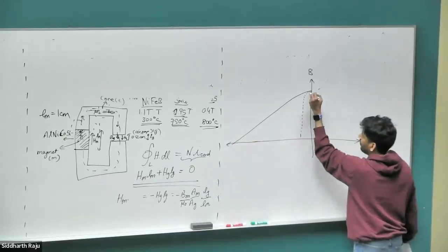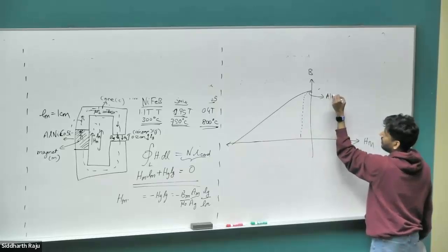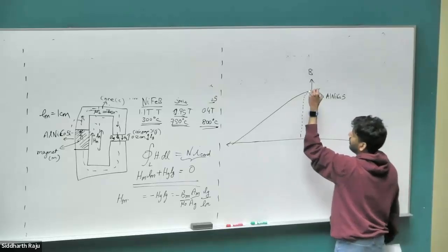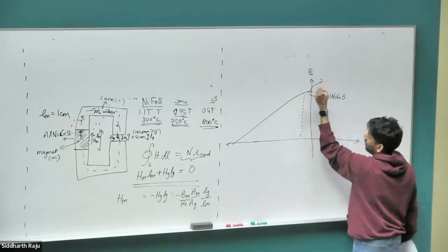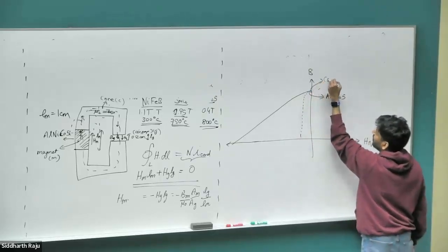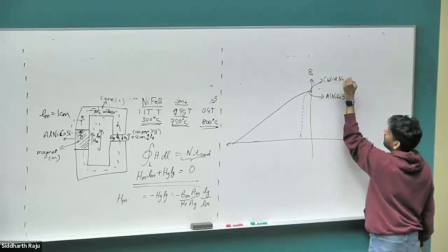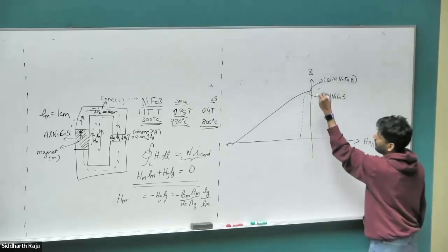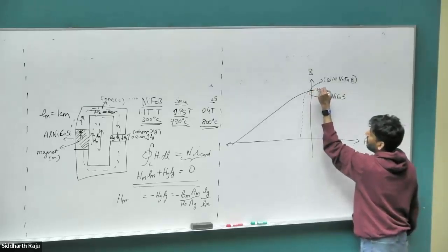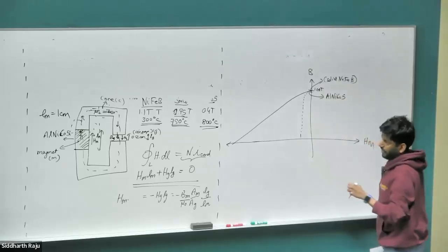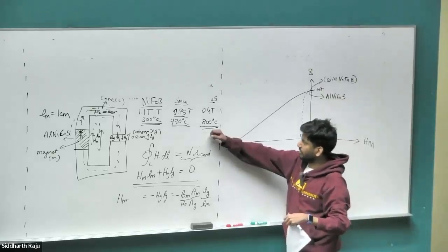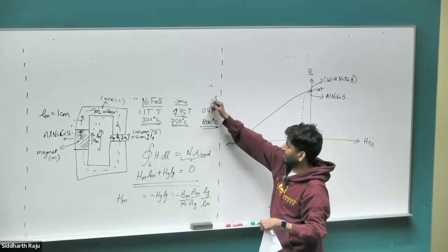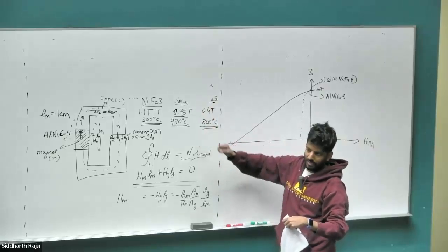So this is the BH curve of an Alnico 5. On the RHS, the second quadrant, the solid non-dotted line is for neodymium. Both of them have a retentivity of about 1.25 Tesla, more or less. But when I wrote this value here, I said that the magnetic field you can get in a typical air gap with the Alnico 5 is around 0.4 Tesla.